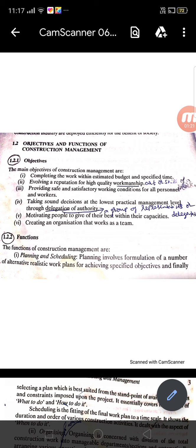And the second one is that you require resources. Second objective, resources like men, material, labor, space, funds, equipment, machinery, etc. Men in the sense of engineers and laborers like skilled labor, unskilled labor, bar benders, carpenters, coolies, men mazdoor, women mazdoor, etc. Materials like fine aggregate, coarse aggregate, cement, tiles, etc. These are a few basic materials.